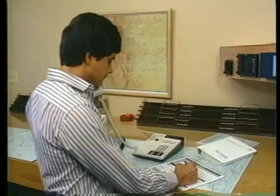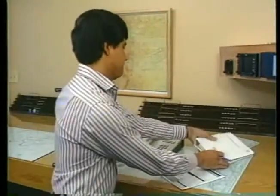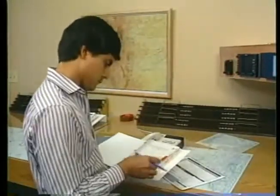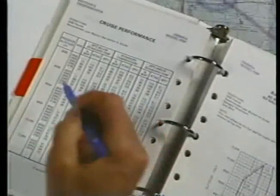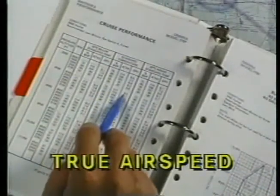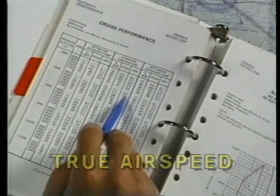The analysis of the winds aloft will usually reveal the most favorable cruising altitude. The altitude you choose should comply with the VFR cruising altitude specified in the FARs. The altitude is also important for determining the true airspeed for the flight. This airspeed may be found in the pilot's operating handbook or by using the flight computer.